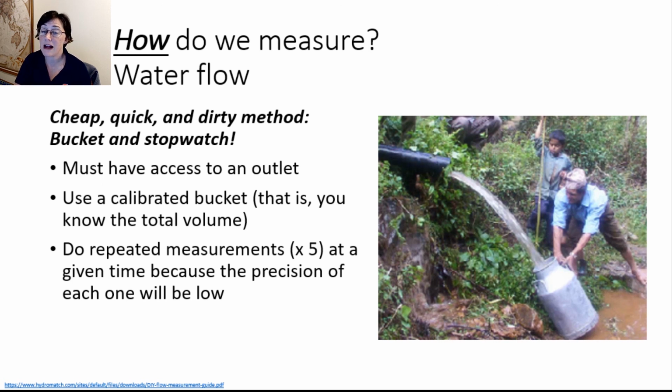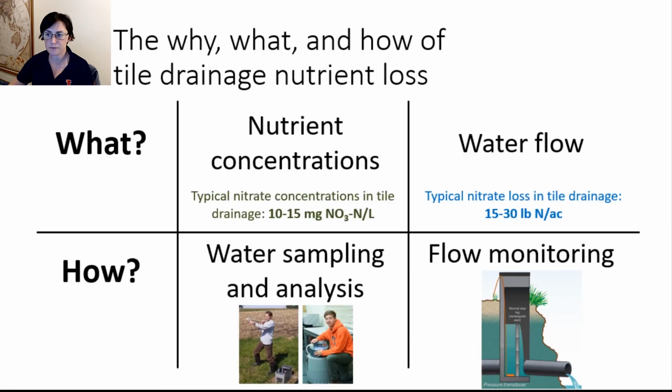Now, while this method is highly accurate, it is not very precise. And so that's why you would want to do a couple repeated measurements at any given time to increase your precision and reduce your uncertainty or variability. However, it's a pretty good option if you're just curious for a quick flow rate.